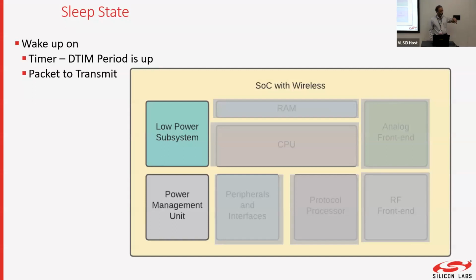So is that better? Or can you retain the state while paying 10, 15 microamps of current in your sleep state? That's a decision the system designer has to make. Very often, the wireless SoC device, including Silicon Labs devices, let the end application developer make his choice. He knows how much time he can wake up afterwards. So he can figure out whether it's better for him to put it in RAM retention power mode or no RAM retention power mode. He can decide dynamically based on the situation what is better.